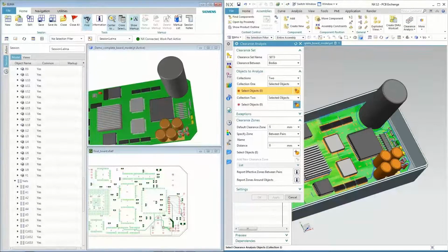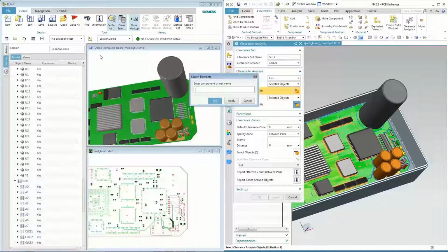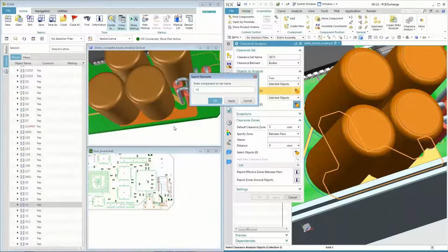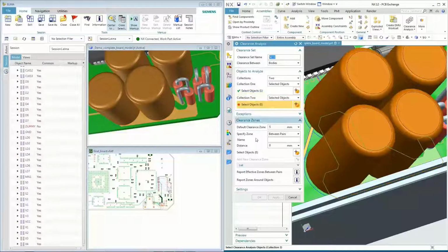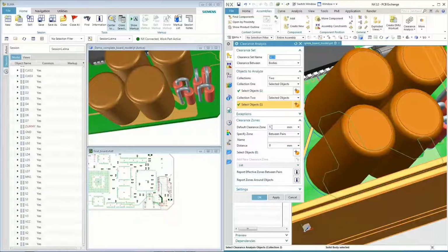It's used to load the schematic and PCB layout data, while CAD takes care of the 3D data. So a Mentor Expedition user can use Alma to cross-select and compare with mechanical design. A CAD file generator can be loaded into Alma while the user is working on the electric design.